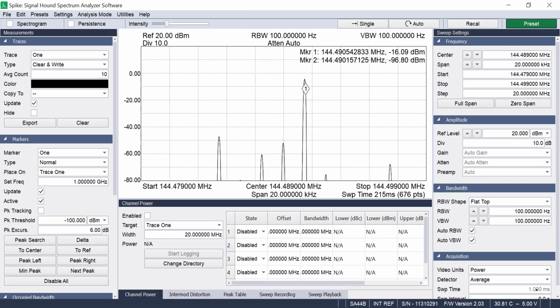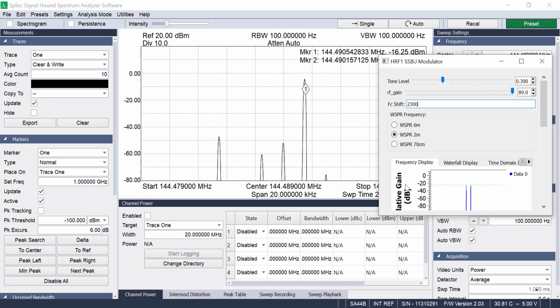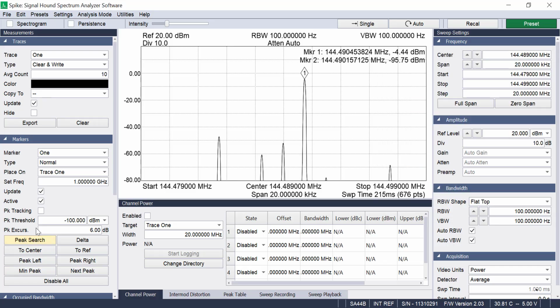So let's go into the spectrum analyzer here. You can see it's drifted a little bit. I'm on the peak search, so typically -4. I've got a 20 dB pad in there, so that's plus 16 dBm. And let's look at the worst spurious here. At 0.3, it's about 43 dB down, which is pretty good.